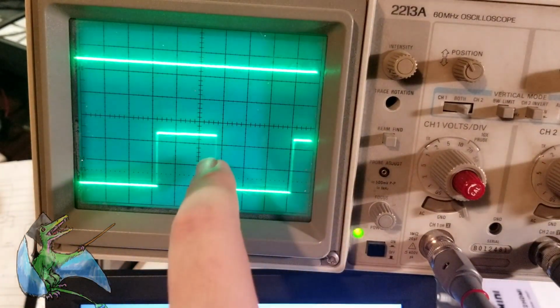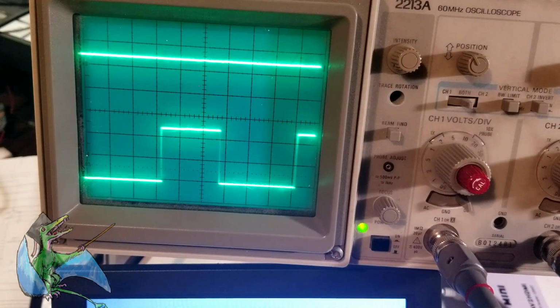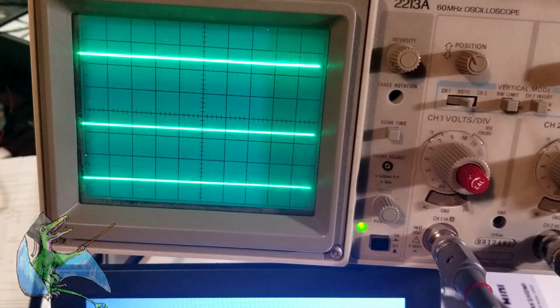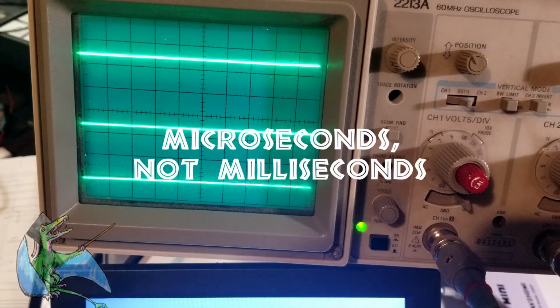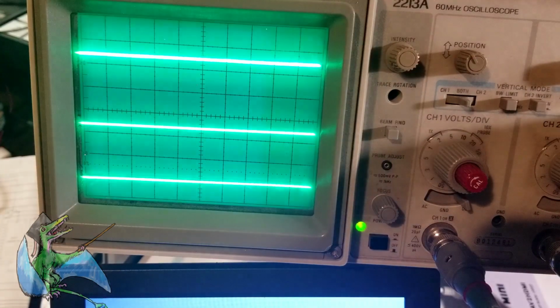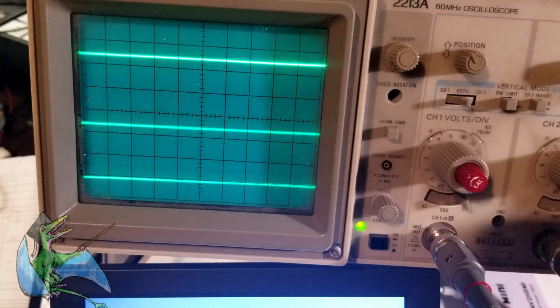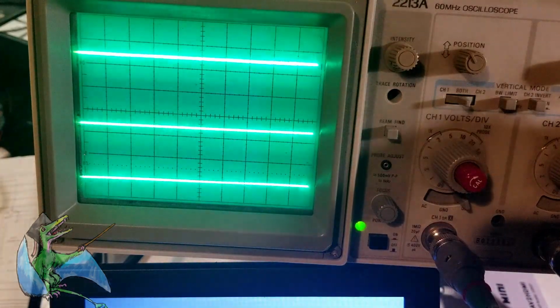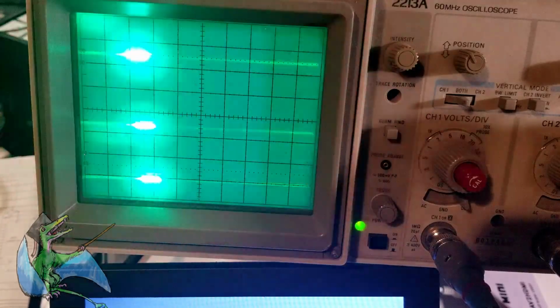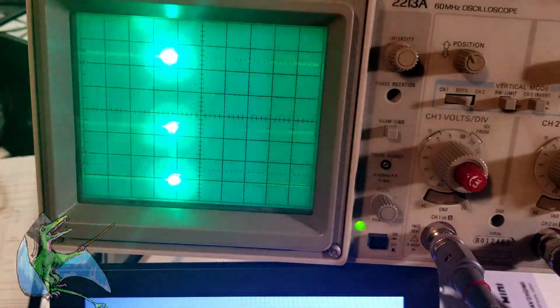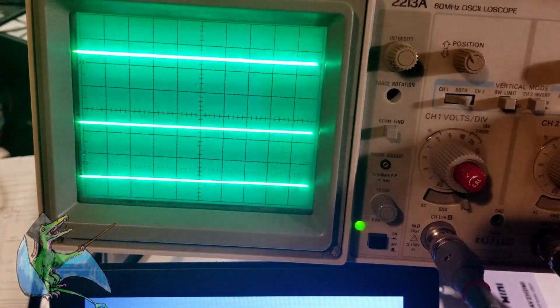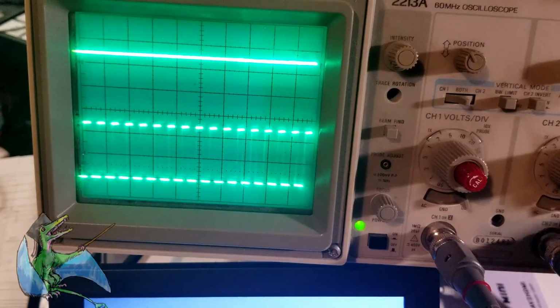We're triggering on the horizontal drive signal again. Let's switch back to trigger from that. There's like nothing. So I had the milliseconds per division set to 10 before, so I'm gonna crank it to, that's faster. Let's go slower. See if there's any more ripple. And that looks really, really clean. So if we flip this back to the other trigger, you can see.